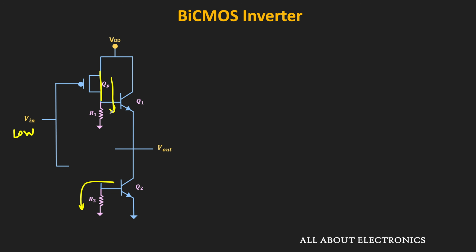Moreover, when the NMOS and the PMOS transistors are in the on condition, these resistors R1 and R2 will also take some of the drain currents of the QN and the QP, and hence effectively that will reduce the available output current of the logic gate.